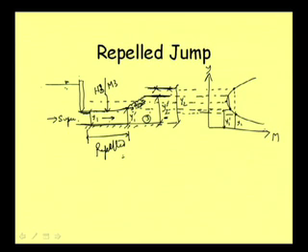But before that, it can damage the bed, it can cause erosion to the bed, and that is why we need to put a concrete bed in this portion, up to the hydraulic jump. So, if the jump gets repelled by a significantly longer distance, then the concreting required, or the safeguard required to the bed, will be longer, and the cost will also be larger. And when the cost is larger, we become very much concerned about what can be done.